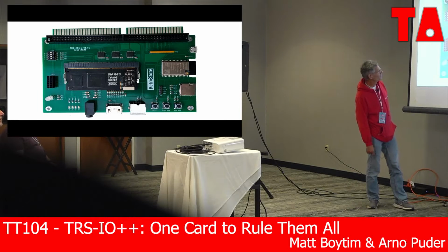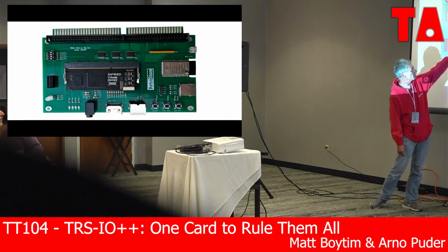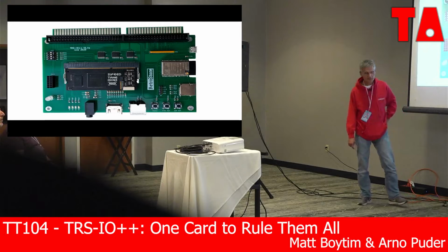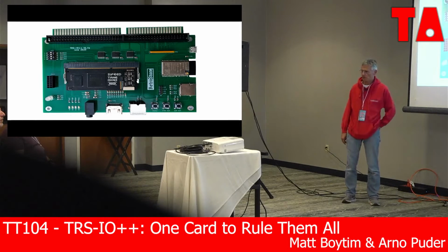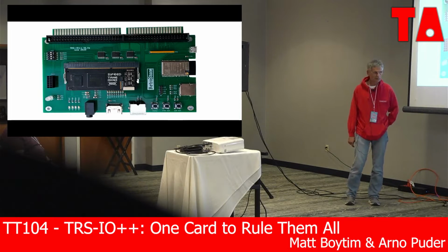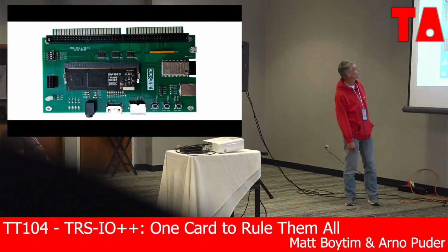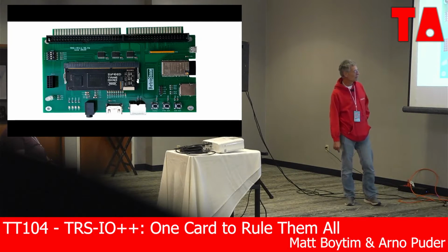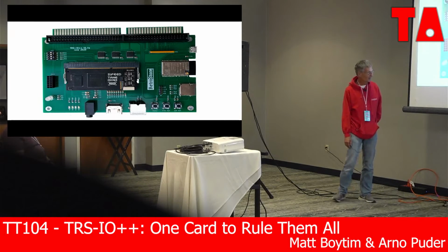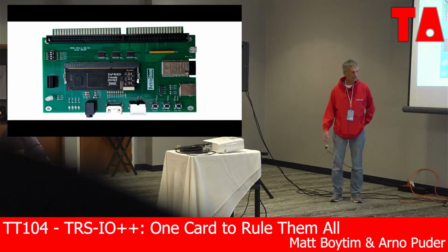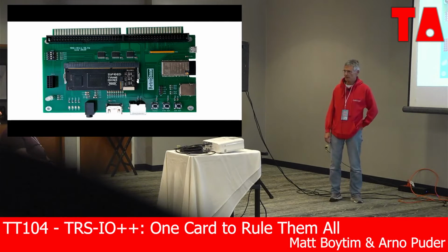And most of the ICs you see, the 3 up here, and there are actually 2 that are hidden under the FPGA module, are just level translators. The FPGA is predominantly 3.3 volt, and we need to interface with 5 volt devices. So that's really about it. It's almost literally a 2-chip solution in connectors. If the FPGA and the ESP32 were 5 volt compatible, you wouldn't really need anything else.